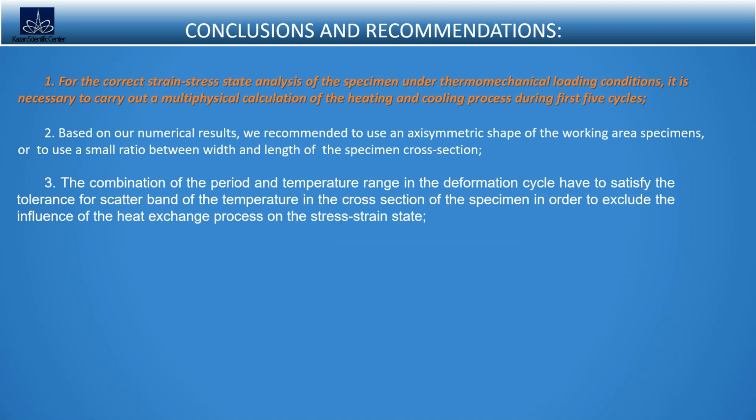The combination of the period and temperature range in the deformation cycle has to satisfy the tolerance for the scatter band of the temperature in the cross-section of the specimen in order to exclude the influence of the heat exchange process on the stress-strain state.